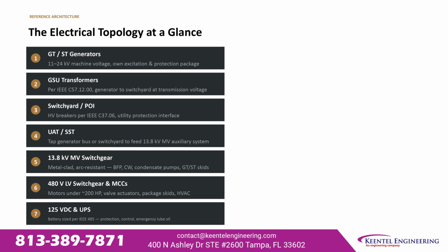Metal-clad arc-resistant medium voltage switchgear feeds the large plant loads: boiler feed water pumps, circulating water pumps, condensate pumps, and turbine skids. At 480 volts, switchgear and motor control centers serve motors under roughly 200 horsepower, valve actuators, and package skids. The 125 volt DC and UPS systems, sized per IEEE 485, provide protection, control, and emergency lube oil power.